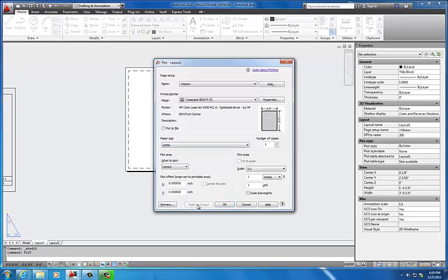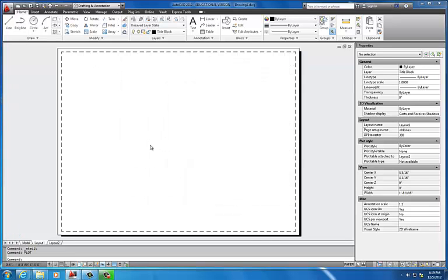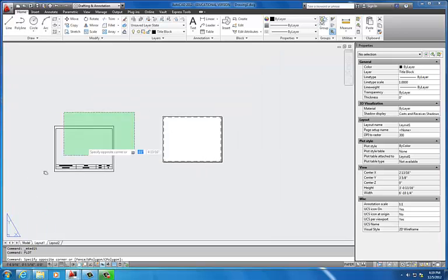And very important, do not print it. Do not hit OK. Just hit cancel. We're just applying to layout. We're just setting it up for now. Right now, if it printed, it'd be a blank piece of paper. There's no point printing. So I'm going to apply to layout and then just cancel. And that sets up my piece of paper the way I'd like it.